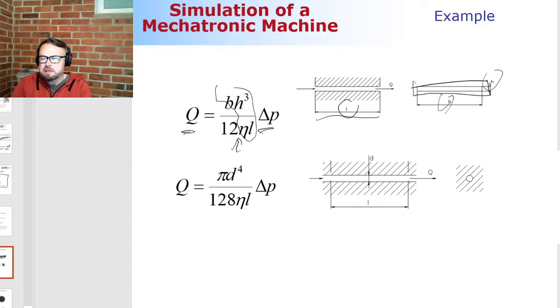Using these parameters, you can substitute all the geometrical information here. Remember, this is viscosity. The viscosity is what affects this type of laminar flow. What about a more common throttle, like a drilling, which has a length of L? The diameter of the drilling is D, so it's D to the power 4 multiplied by pi divided by 128.